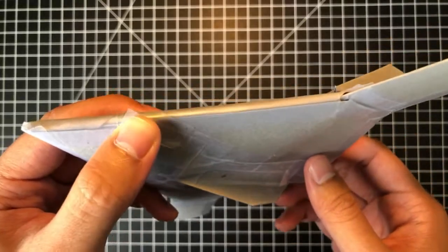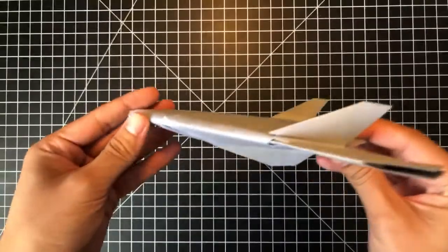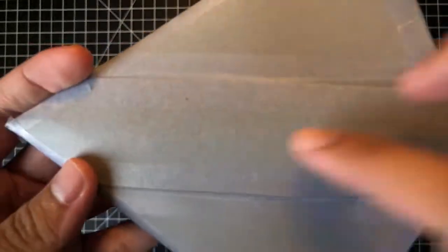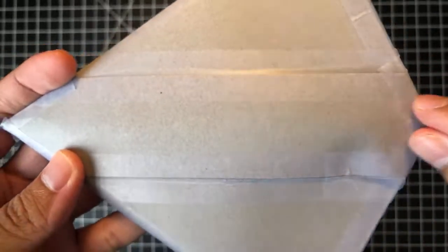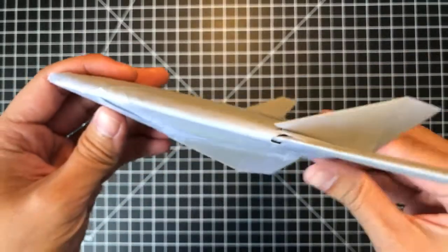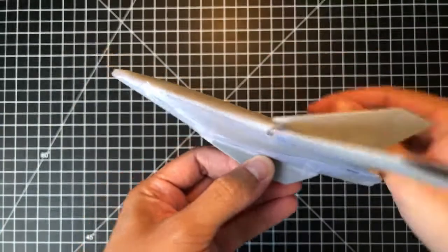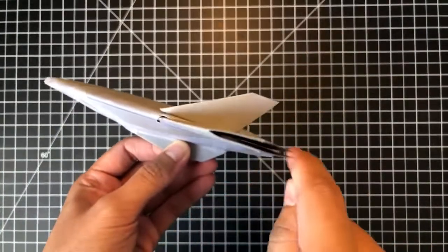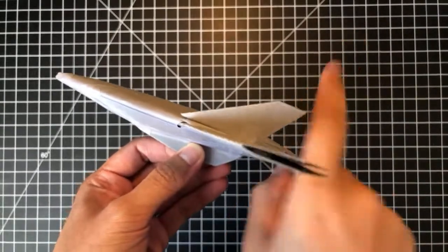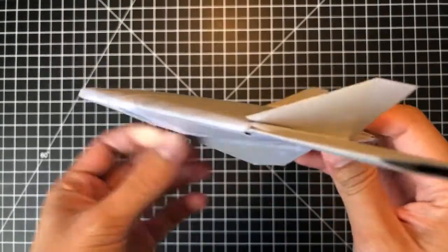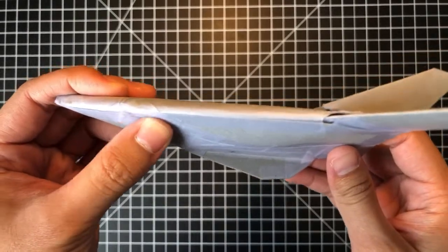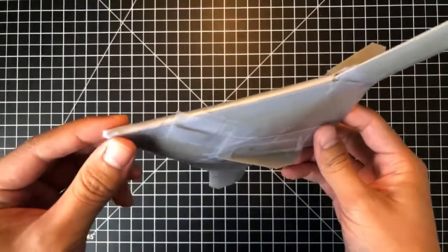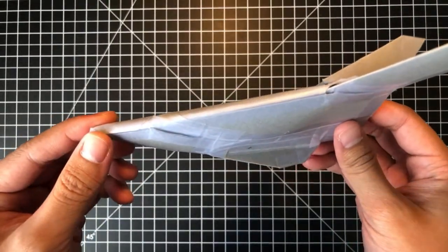Essentially what happens is, you have your aircraft flying through the air. There's going to be drag, right? There's going to be skin friction, just the air rubbing on the actual skin of the aircraft, as well as pressure drag. Because if you're at an angle of attack to create lift, there's going to be some component that's acting in the back direction, which is drag. So essentially your velocity decreases over time, and what happens with that is you lose energy really, really quickly.